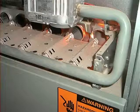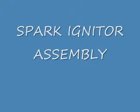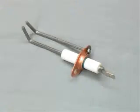This is a hot surface igniter. It has a hot element that heats up and glows every time the ignition sequence is initiated. This is a spark igniter. When heat is called for, the igniter will fire off much like a spark plug. This ignites the main flame directly, without use of a pilot light.